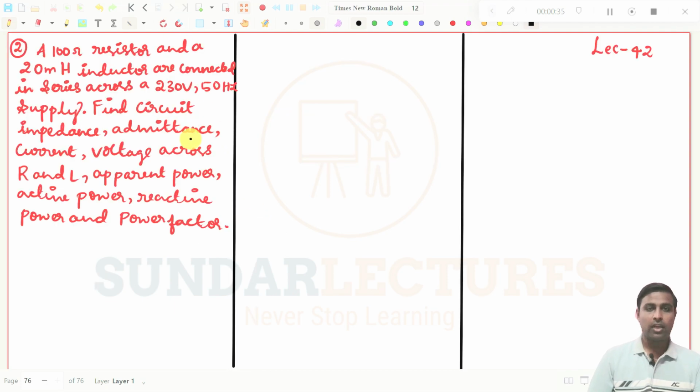And now in this class we are going to take the RL series circuit, right? What is the question given? A 100 ohm resistor and a 20 millihenry inductor are connected in series across a 230 volt 50 hertz supply. Find circuit impedance, admittance, current, voltage across R and L, apparent power, active power, reactive power, and power factor. So this is the question given.